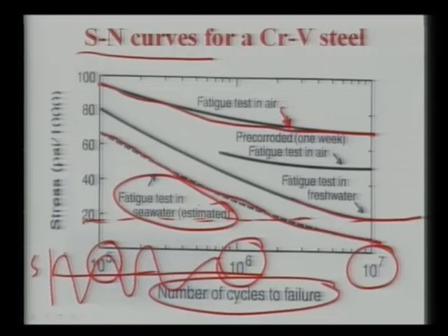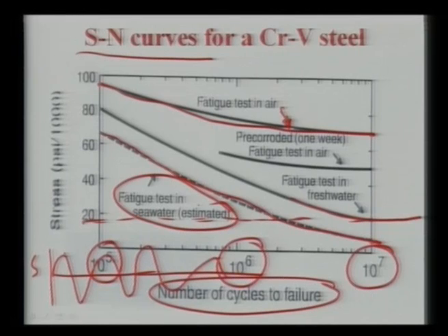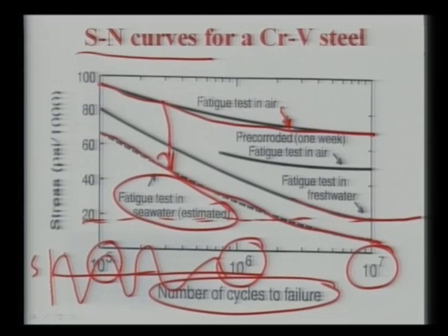Therefore you cannot really use the fatigue test data of any steel materials which you have obtained in air, but you have to rely on the fatigue test data which you have obtained in seawater, for example, so that you can conservatively estimate the typical fatigue life of that steel in real in vivo condition, because you can see there is a large decrease in the fatigue strength when you compare the fatigue data in air with that of the fatigue data in seawater.